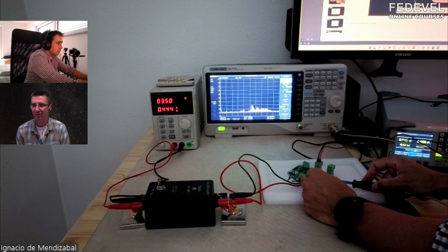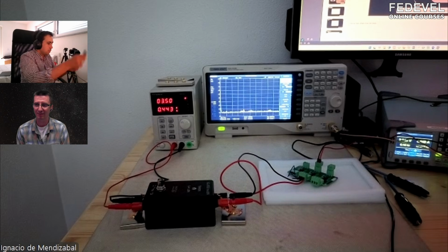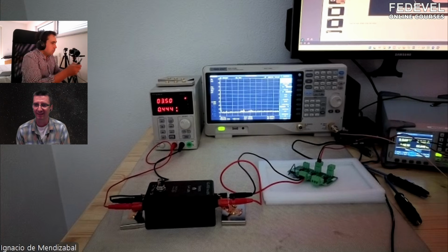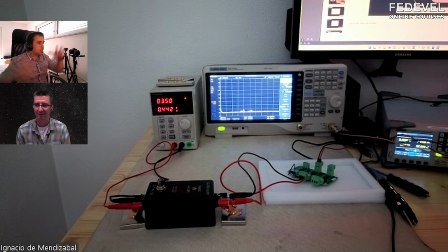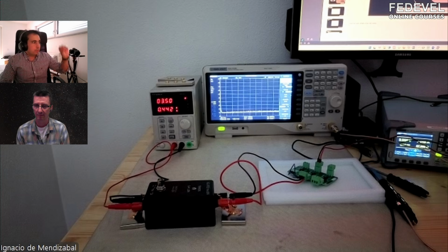So it's very important to actually start with the big one, because you can very easily miss. You just move it a few millimeters away, and then you will never measure it. Yeah, definitely. So always start with the biggest probe, then look for an area and identify it, and then start using a smaller one that allows you to move around the system, and that lets you identify when the signal is there and when it is not there anymore.